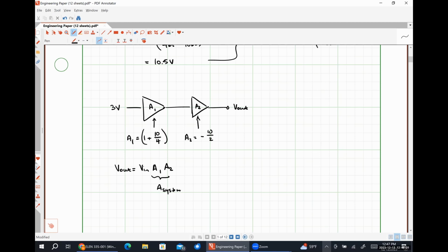We could take the difference of two signals and then integrate that output or something by cascading a differencing amplifier into an integrator, or cascading a differencing amplifier into a differentiator, or we might want to take the integral of a combination of input signals. But it's all just simply putting the stages in the order that we want the mathematical operations to occur, right? So this is very, very boring because it's just scaling twice, and we could have accomplished this with a single amplifier, but I was just trying to show you how it worked.